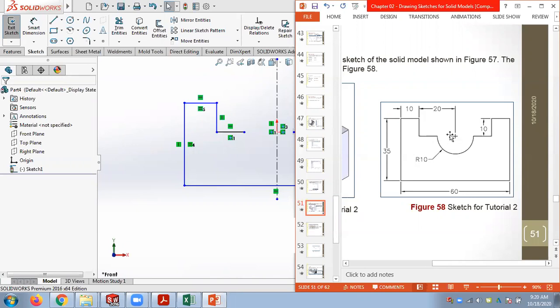So if you carefully look at this drawing, you can make this line equal to this line and equal to this line even. So all these three lines are 10. I am looking at the dimensions and deciding it, and these three lines are also 10. So we can reduce our dimensions further. We don't need to give this 20 even at the end of the day.